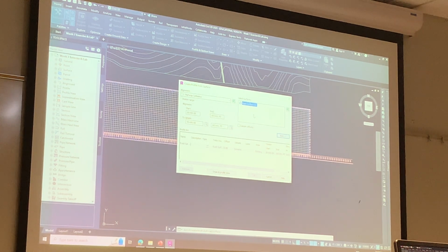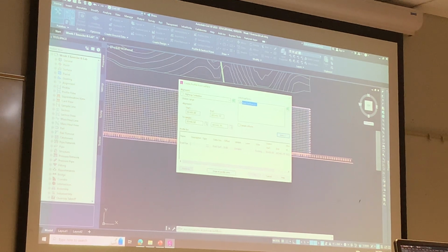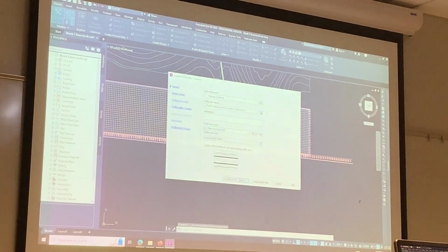I believe next week we are going to have Civil 3D create a second surface for us by using our proposed profile and cross section. So there will eventually be multiple surfaces here, but we select the proper surface. We want to create an existing ground surface, so we would click Add, and we click Draw on Profile View.